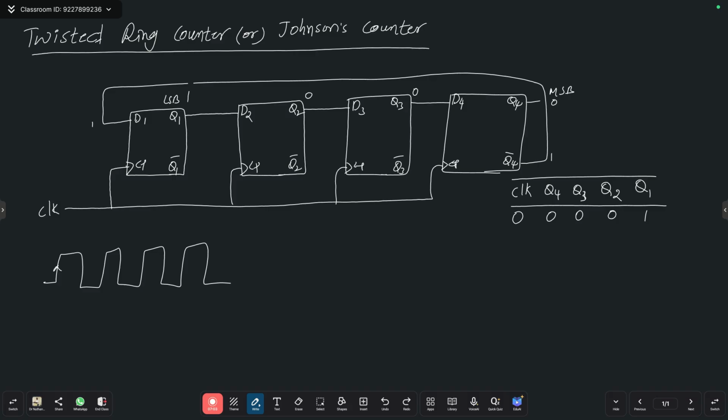Now what I am giving? Supply is given, means your clock will be 1, edge clock. Then the first flip-flop is going to trigger. When the first flip-flop triggers, this will come to here. Only D flip-flops are going to transfer the data, push the data. Yes or no? There is no other operation. Then this 1 comes to here, this 1 comes to here, this 0 comes to here, this 0 comes to here.